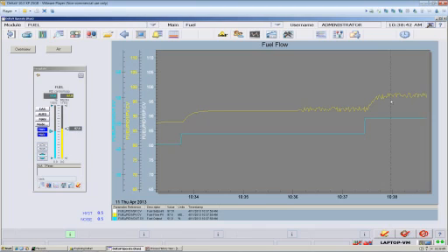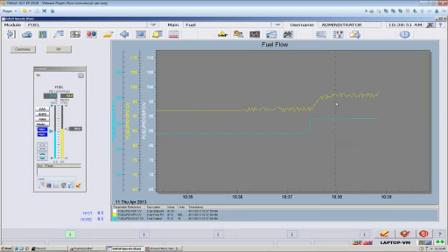Now in this perfect simulator world, I know that the real time constant is 8 seconds, and by my quick and dirty estimation, I estimated 7 seconds. I'm not worried about that a bit. The fact that we're 7 versus 8 is just fine. The results will be perfectly predictable, perfectly stable. I'm worried about not putting in 40 when it should be 8, or not putting in 1 when it should be 8. The difference between 7 and 8 by this quick estimate is not worth splitting hairs over.